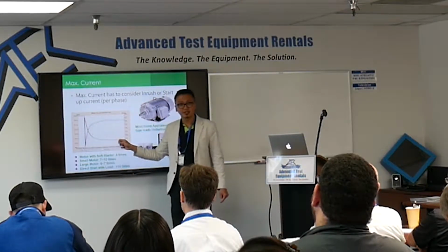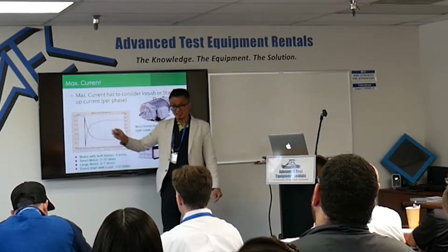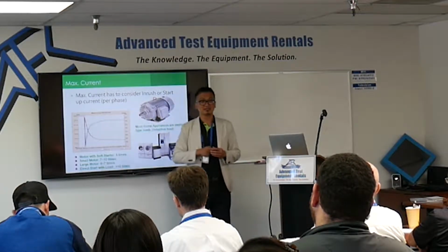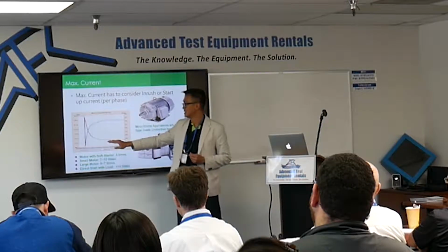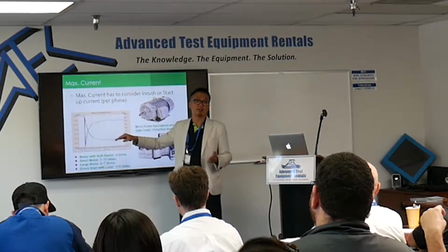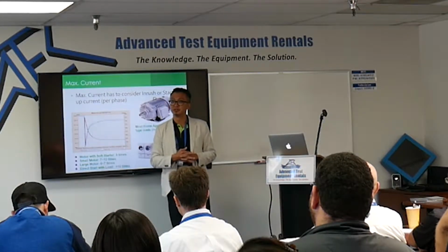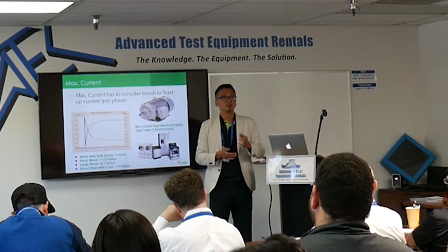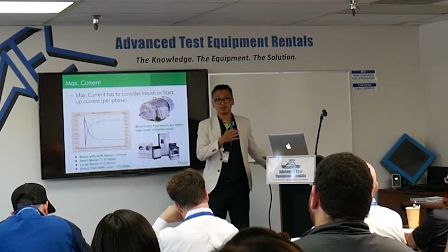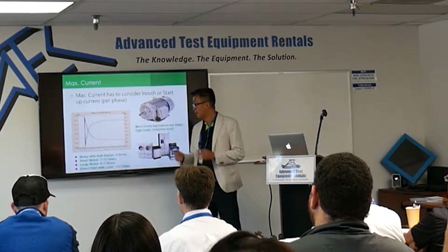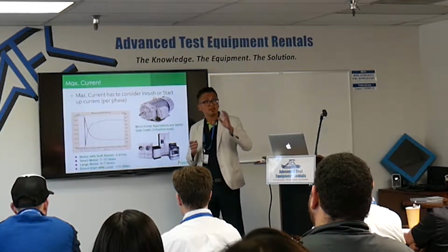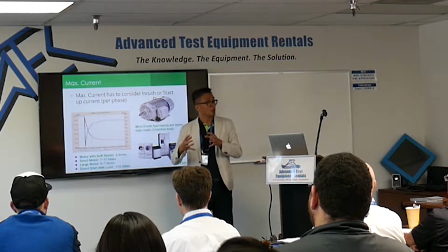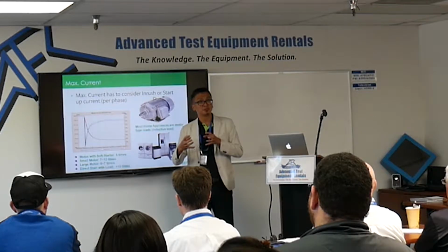Sometimes the rated current and the inrush differ, so does everyone guess what the difference is? In your experience, how many times the rated current is the inrush typically? 3 to 5 times, typically. Right, 3 to 5 times is very typical. That is without any load. It's usually 3 to 5 times.